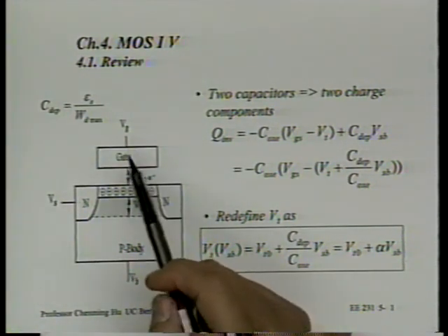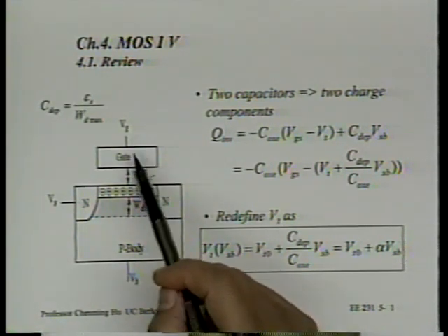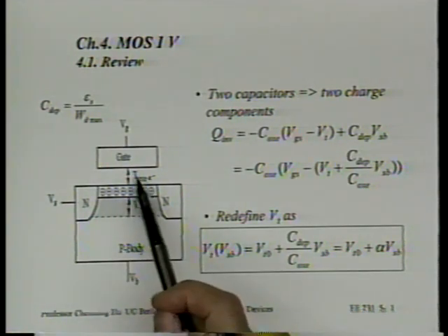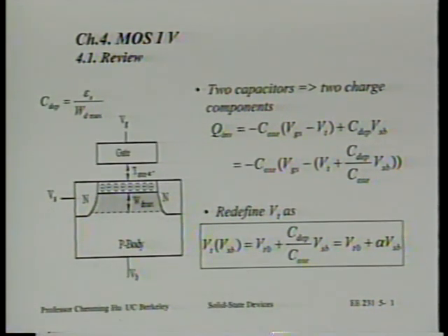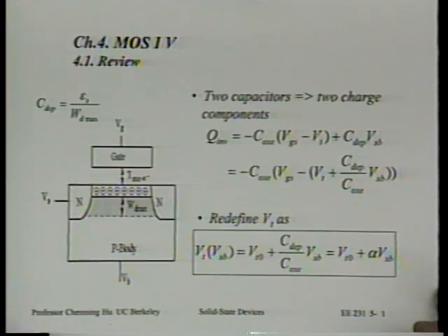For example, just as the front gate can modulate the electron inversion layer charge density with a voltage applied to the front gate, so can the back gate modulate the density of inversion layer charge with a voltage applied to the back gate. You see that? These two things are really the same. They perform the same function. See that? All right. So the front gate has a thickness called a T ox. The back gate also has a dielectric thickness called a WD max. Right? Other than that difference, the function of front gate and back gate are very similar. So we'll make use of that symmetry, and I think that will give us a useful picture of how to think about the effect of the substrate.